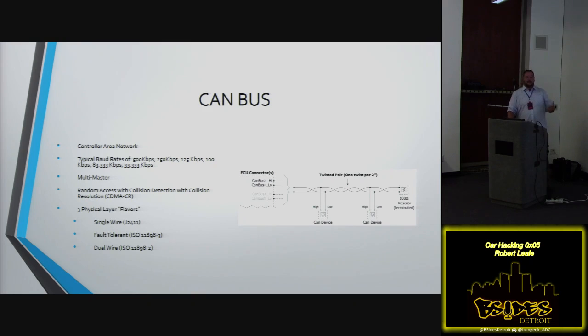There's different baud rates, but you can see it typically goes up to 500 kilobits per second. So it's not super fast, right? We don't have super duper high speed with CAN bus. What we have is high reliability and short packets, really quick messages that deliver the information and then shut up, right? Here's your data, real quick. What's your engine speed? That's it. Really small packetized pieces of data that don't need to be big. There are no long messages, not very verbose, right?